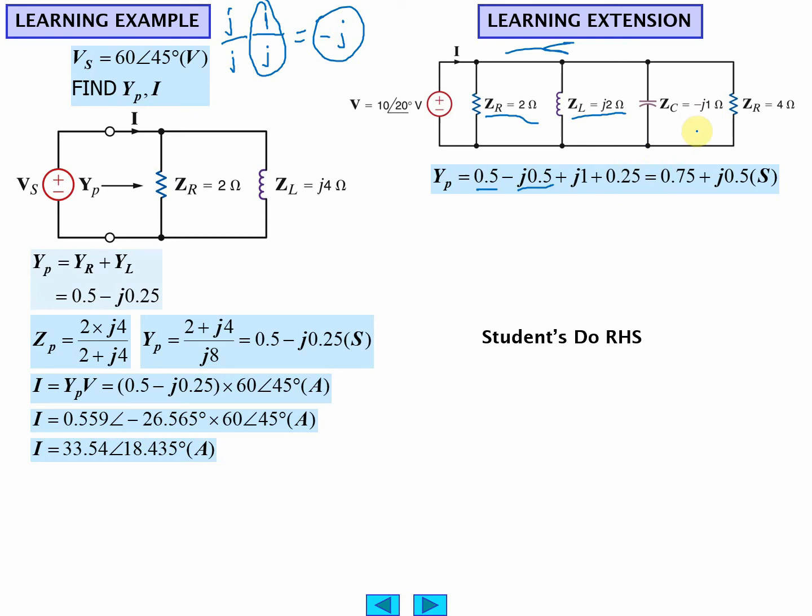So the reciprocal of this would be positive 1J. The reciprocal of this is 1/4. Simple. And then you just collect terms now and convert that. You can use the absolute value function and the arg function in MATLAB or GNU Octave to find the angle. The arg function finds the angle, and the absolute value function finds the magnitude.